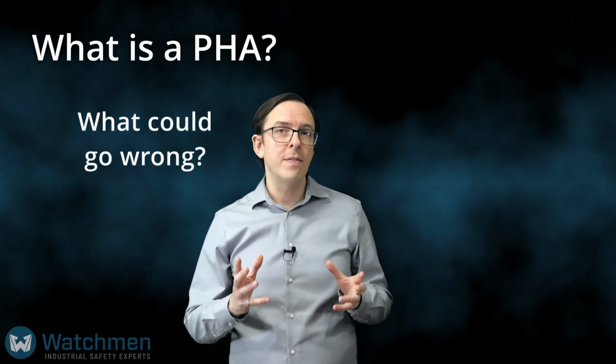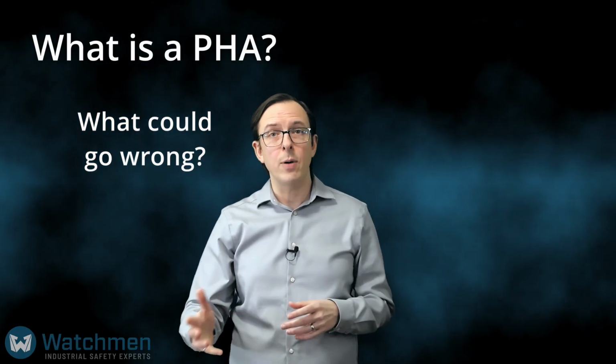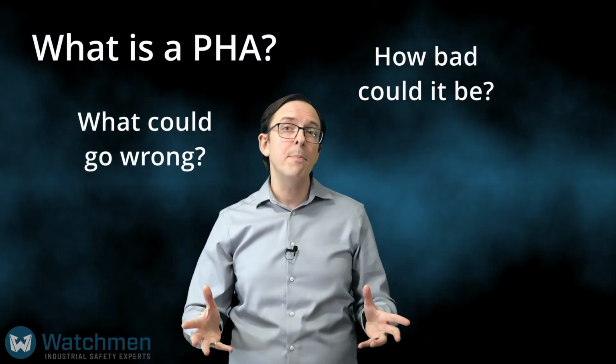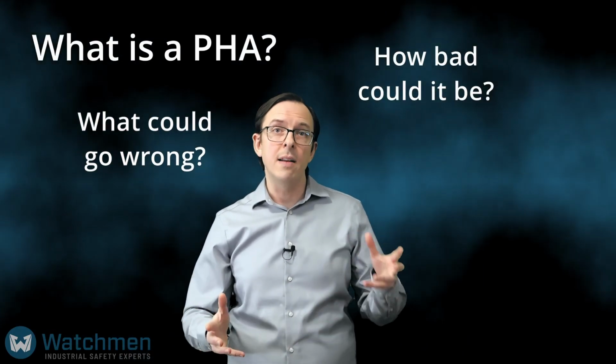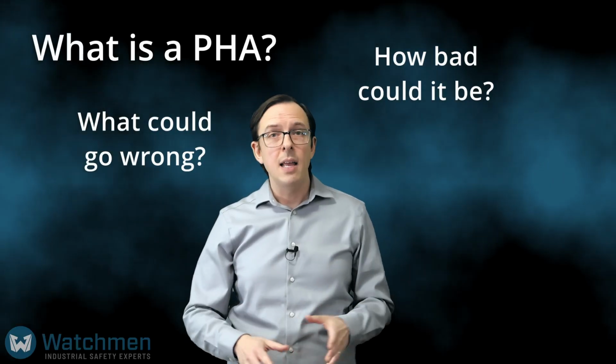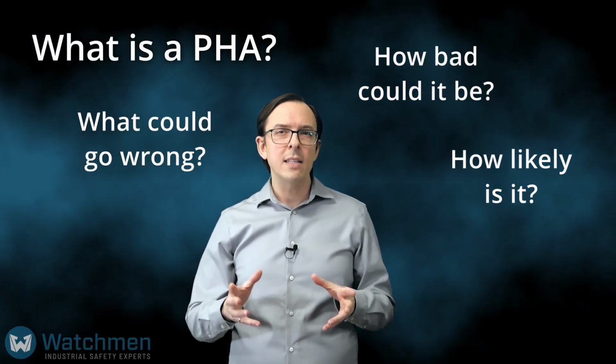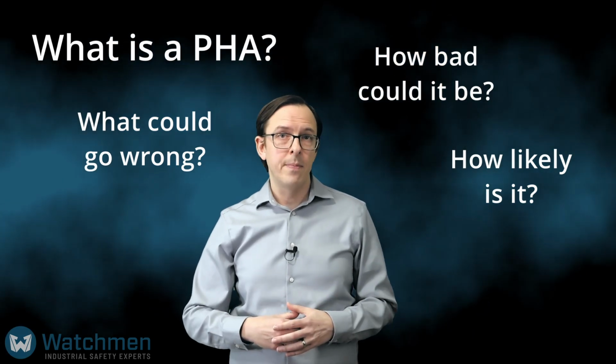Regardless of the methodology, each type of PHA is designed to answer the following questions. What could go wrong? We look for failures or deviations that could lead to a hazardous scenario. How bad could it be? How big of an impact could this have on personnel, the environment, equipment, and production if nothing happens to stop it? How likely is it? What is the chance that it will actually happen here?